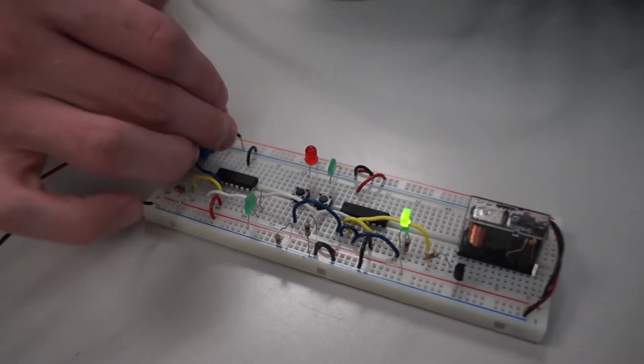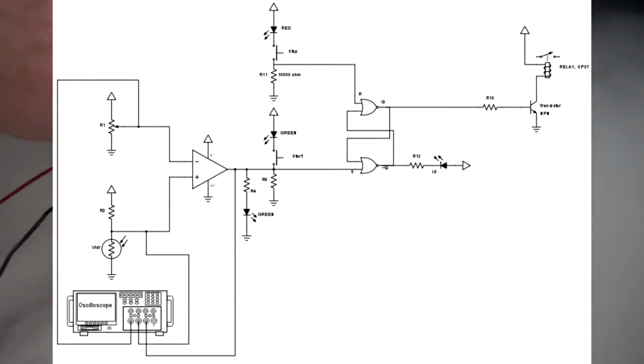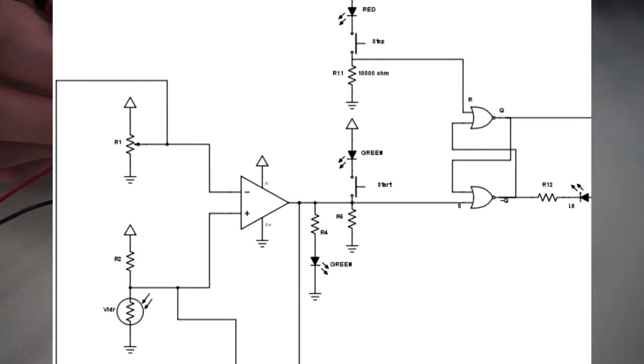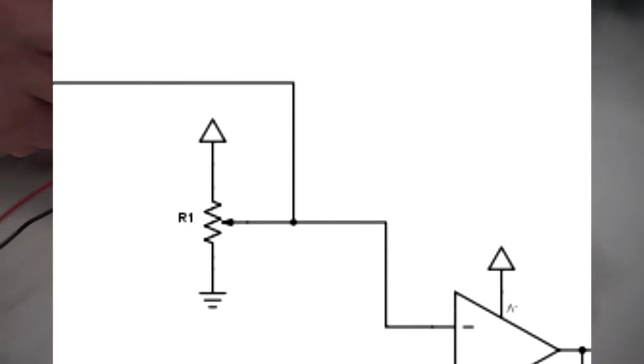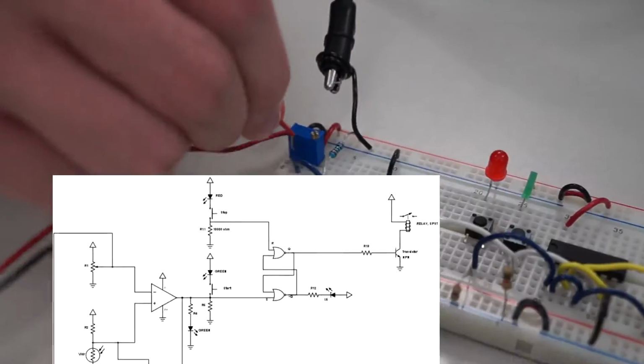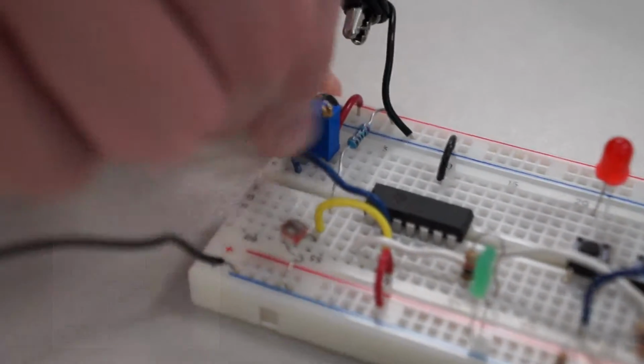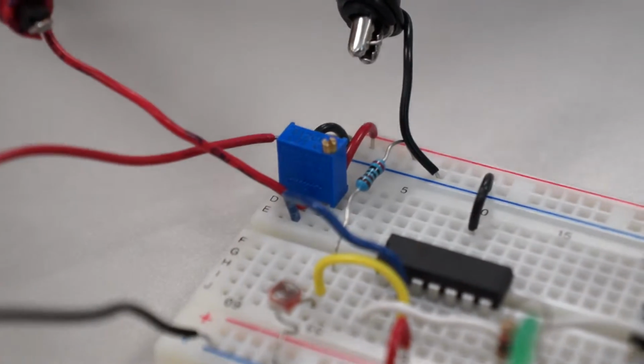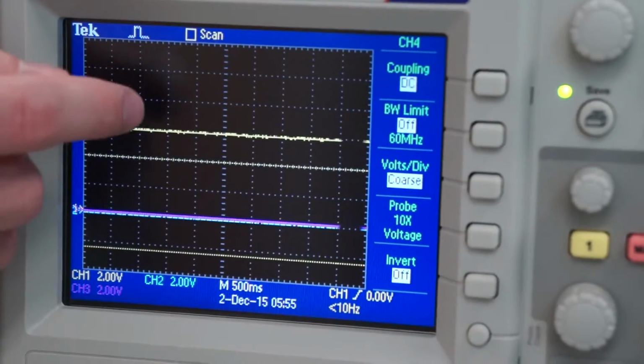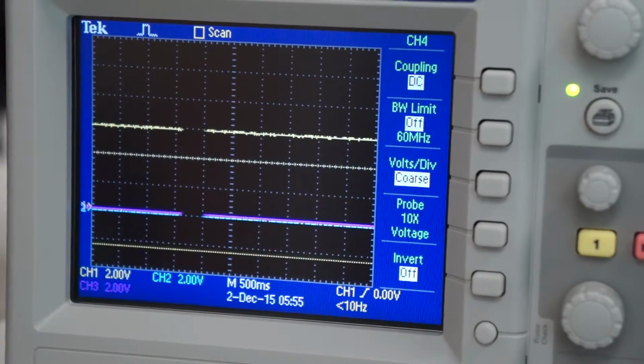So first we have to plug in this to ground, and the first part of the flowchart subsystem tells us to check if the voltage out of the trim pot is working. So we plug into the base of the trim pot right here, and then our oscilloscope now shows that that voltage is 12, so that output is proper, and the trim pot is not the problem with the first subsystem.